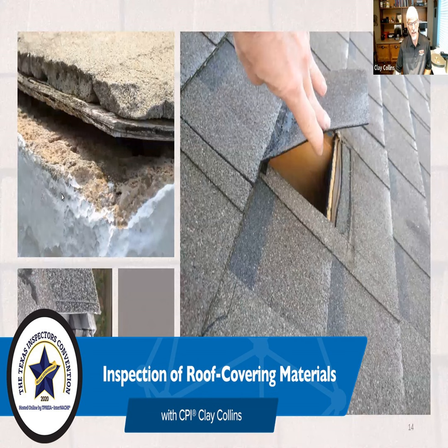And the source of that hole appeared to be from a toe board that the installer had laid horizontally along the roofing, nailed it in place, and removed the toe board after the roof was installed and caulked every nail hole but that one. So it took 13 years for that one small leak to turn into all the damage